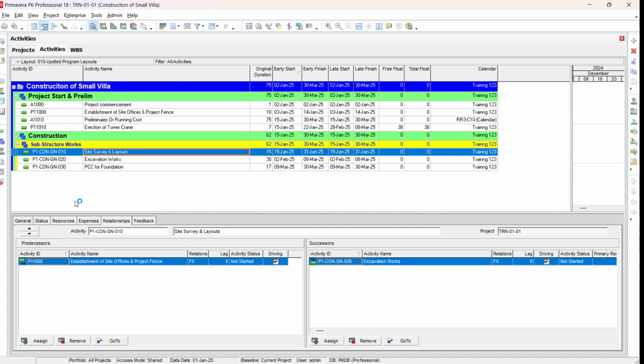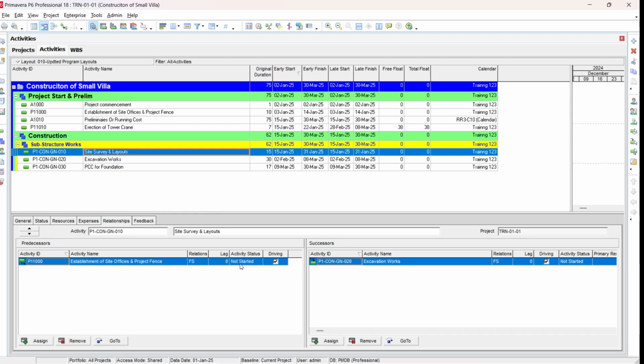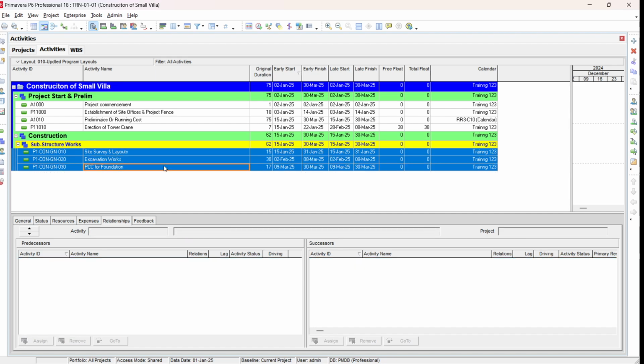External here does not mean from another program. It is the same program here, but it is outside the selection. So if you have this selection, the activities between these selected activities will be copied with the relationships between them, but any relationship coming from outside of this selection will not be copied. So most of the time it is required to copy them.